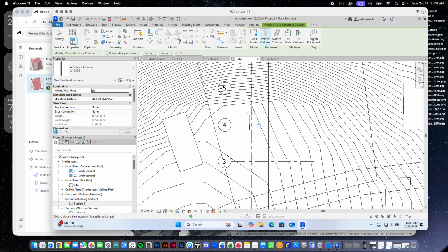We'll also start to utilize some special copy and paste tools that we can use to paste things at multiple levels. And we'll look at the section in those levels, start to establish top of steel, a second floor, a third floor, the roof, et cetera, right? So we'll just start to make the big grid that we can then start to make decisions within, right? So it's sort of a matrix that helps us align edges and centers up to, okay? All righty? I can't wait. It's gonna be so great.